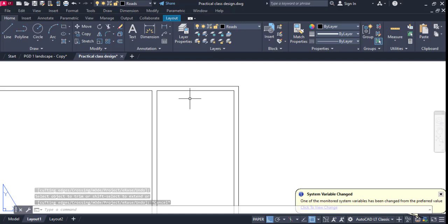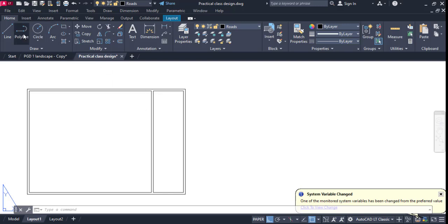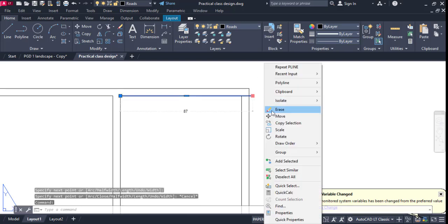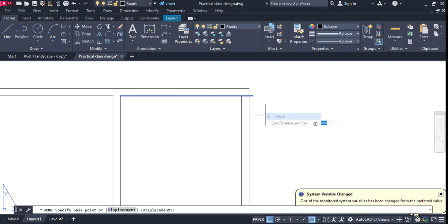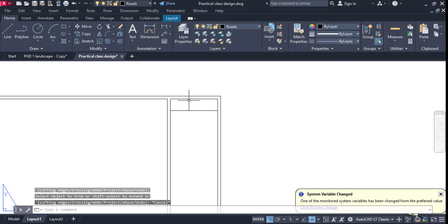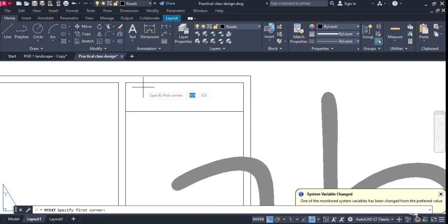Now there's something you must note. Our settings for our text are in millimeters, but here I'm working with meters. So what do I do? Let's assume I just want to create something small and move this down here. I want to create my legend here, so I come and say, okay, text. Remember now, you see that the text is very big, right?